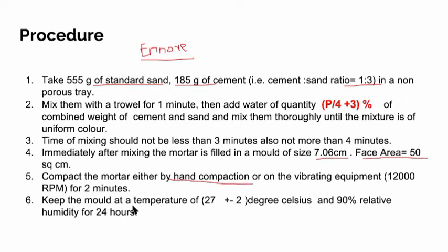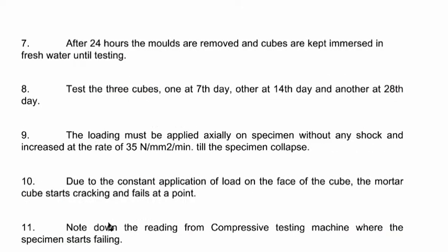Keep the mold at a temperature of 27 plus minus 2 degrees Celsius and 90% relative humidity for 24 hours. After 24 hours, the molds are removed and the cubes are kept immersed in fresh water until testing. Test 3 cubes, one at 7 day, other at 14 day, and another at 28th day.